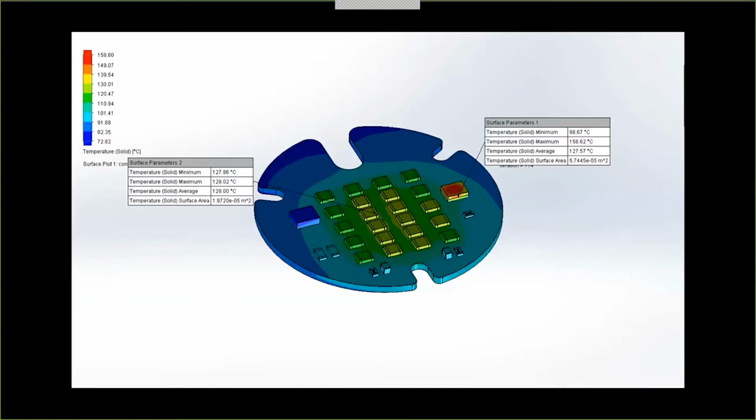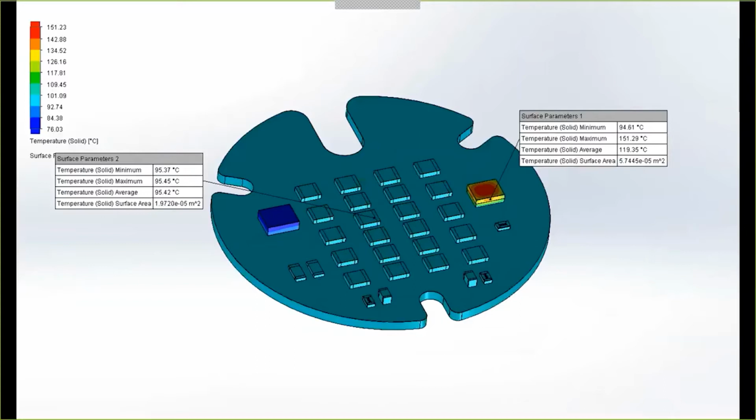So the next step was, we said, it's a simple circuit board. Can we make it one-sided and dump it on a chunk of aluminum, an aluminum core circuit board? Price is usually the same for small runs, for larger runs, costs a little more. But you can see here we got a pretty decent gain in, I guess it's loss in temperature. The LEDs are now below the design temperature by 5%, which maybe isn't completely ideal, but we're in the realm of possibilities. And we're at 5 degrees Celsius below our average temperature for that constant current source. Again, we're in the realm of possibility, but not ideal.